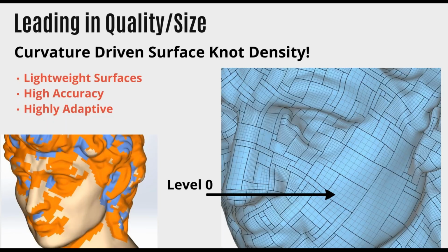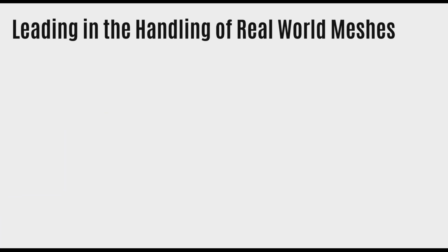So for example, there's a level 0 surface on the cheek there, which has a very low knot density; these are the knot densities, that basically show the level of geometry on the surface. And there's a level 1 surface, and there's a level 2 surface. So you can see that the knot density increases. Now, if we had to do this whole model at level 2 in order to get the detail in that particular area of the eye, the weight on it would increase by approximately a factor of 8. So that's how important it is to do these things at different levels.